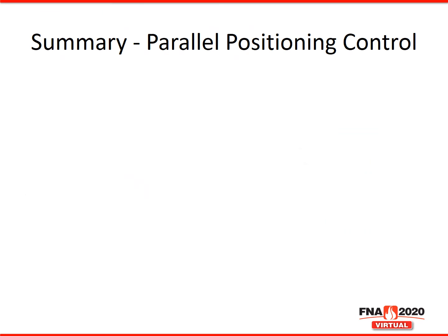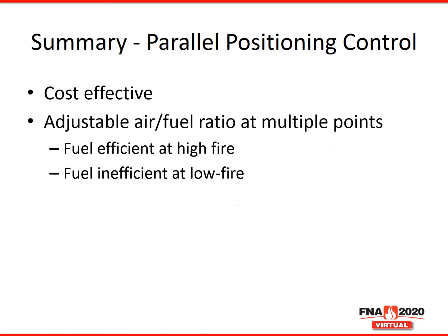Let's summarize parallel positioning. This control method is cost effective. Electronically adjusting the air-fuel ratio based off the firing rate is beneficial for optimizing for the requirements of the job. Can obtain good temperature uniformity by ironing out hot and cold spots by tweaking the air-fuel ratio.